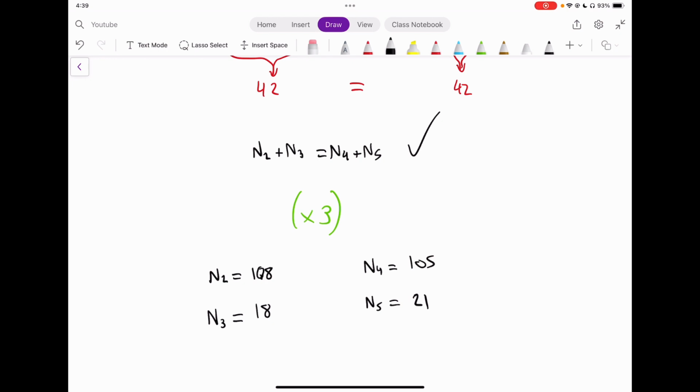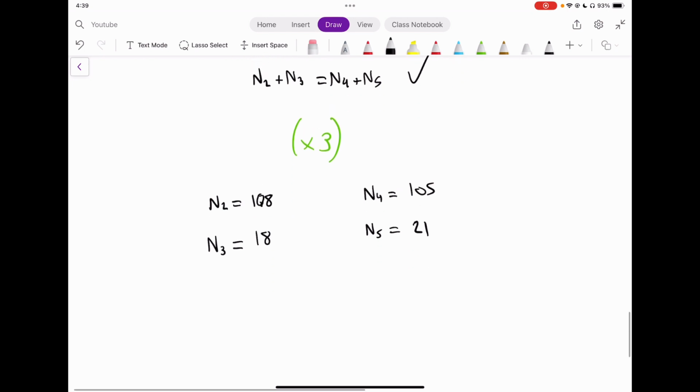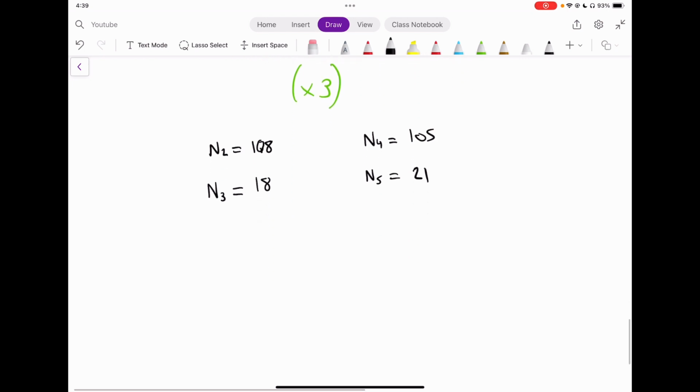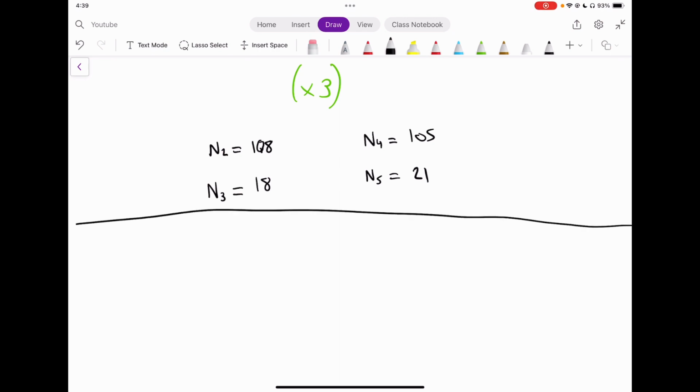Okay, I hope this makes sense. If not, rewatch this part of the video, and there will be some more thinking about that a little bit later, and you'll be doing a lot of example problems based on that. So moving forward, there are many ways of getting to this number, but the best way is really to do this assumption of N3 is equal to 1, and then you start from there, essentially. You start with one side and you say, my lowest gear or my pinion is going to have 1, and that's how you normalize.